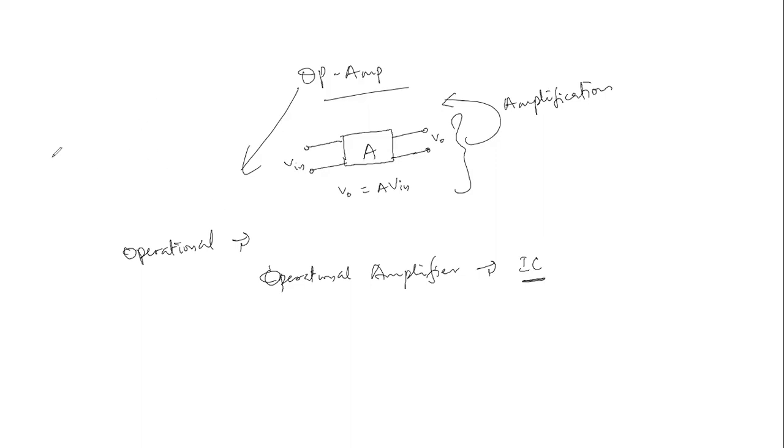So with this, it's worth mentioning here that the operational amplifier, or better still, the amplifier itself, could be modeled using the Thevenin equivalent circuit of a practical voltage source. And there we'll get a voltage source connected in series with some resistor.